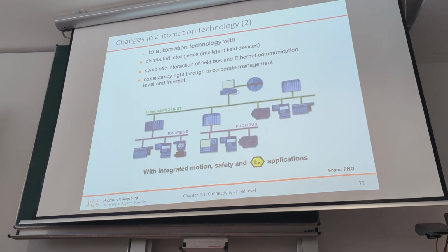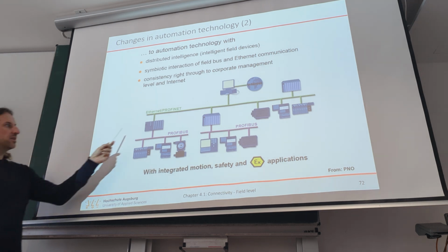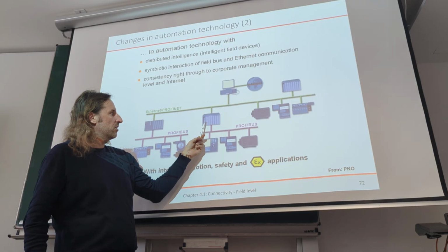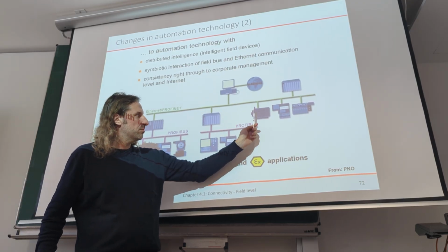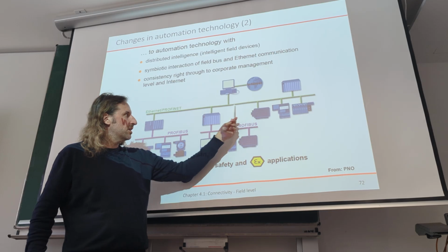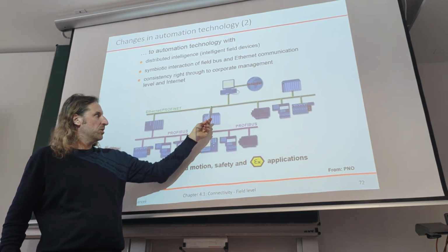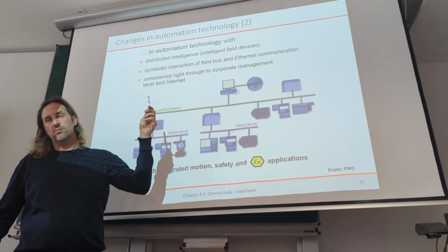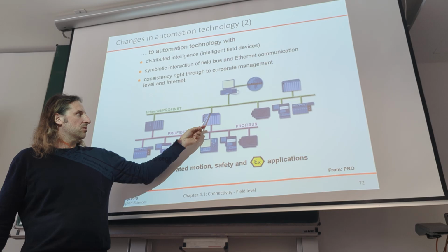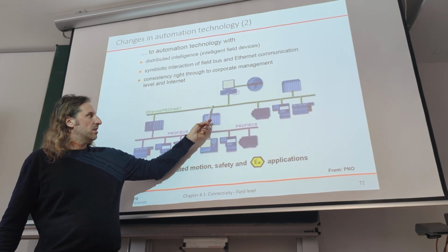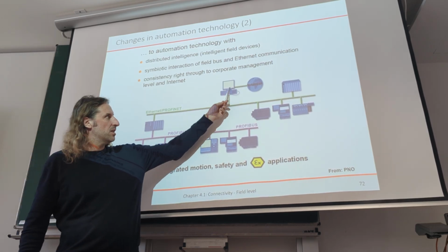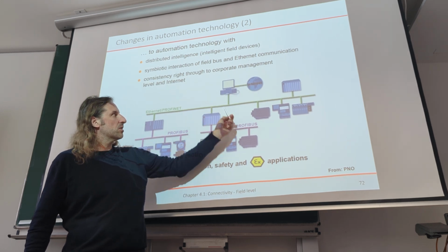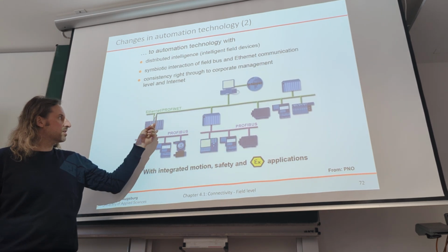So we have an automation system with distributed intelligence, because we can actually communicate. There might be multiple PLCs exchanging information, and they can also use actuators like motors that are connected on the same network. Here we have Ethernet-based systems, so systems based on our IT technology, and they have one advantage: they can easily do the transfer to the internet, because they use the same technology.